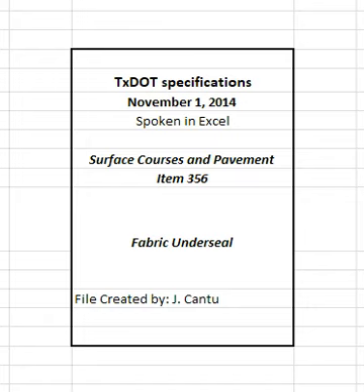2.1.2 Asphalt. Provide the grade of asphalt shown on the plans and in accordance with item 300, asphalts, oils, and emulsions. 2.1.3 Blotter. Provide screenings, natural sand, or other materials as approved. 2.2 Pavement joint underseal. Provide material in accordance with DMS 6220, fabric for underseals, or DMS 6260, reinforced fabric joint underseal, as specified on the plans. Use roll widths as shown on the plans or as approved.